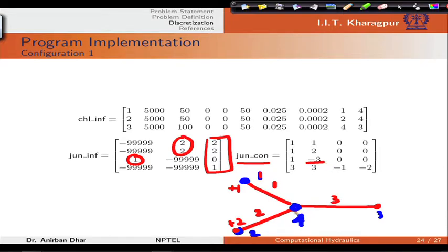and internal junction we have 3 channels connected with this particular junction. So, this is +3, -1, -2 because end section of 1. So, this is -1, end section of 2 that is -2, and starting section or first section of channel 3 connected with this one. So, this is +1 +3. So, this is our channel junction continuity or junction connectivity information.